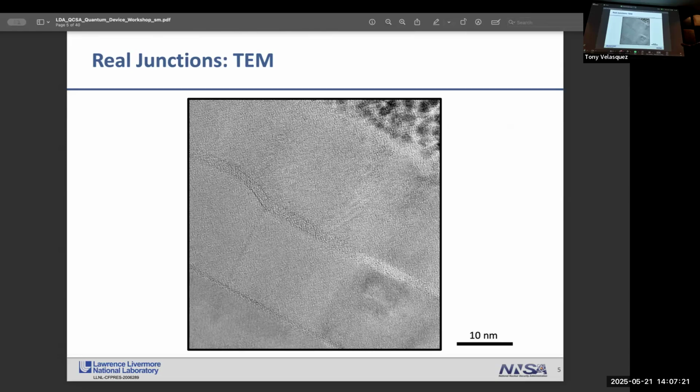And you can see a grain boundary that's moving through the lower aluminum layer, and it's introducing some cusp into the Josephson junction. This is essentially the origin of the uncertainty in the Josephson energy that tends to randomize qubits. So ideally, we'd like to get beyond the shadow evaporation process, and there are many efforts underway to do that.